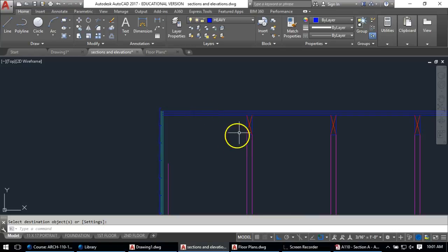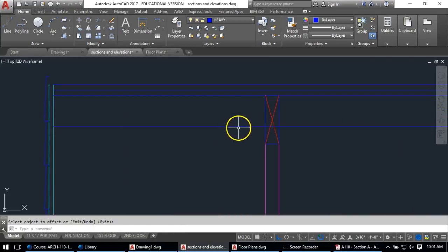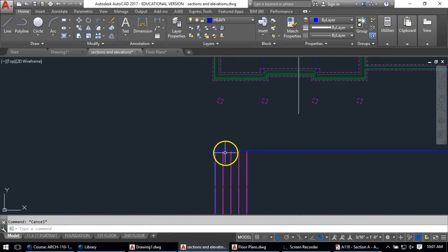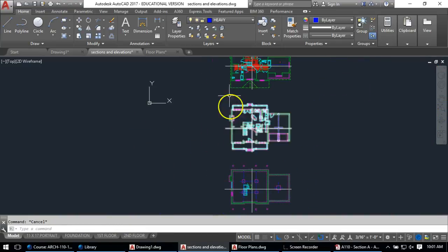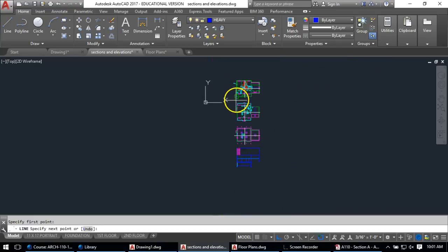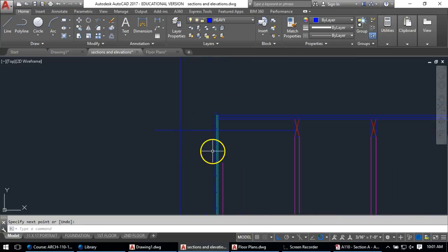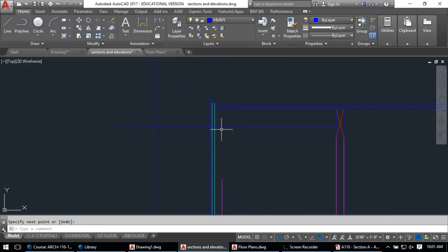So I have a 2x4 that hangs out over from this truss to over to make that little cantilever. So I'm going to offset 3.5 inches down. Now I'm not cutting through that, so it shouldn't be a thick line weight, but it's going to end there. Delete that here, and it's going to come out. And I know my edge of my roof I have for my second floor plan is here, so I can draw a line down, which will be the edge of this overhang, right? It's coming out there. So I have that coming out there.